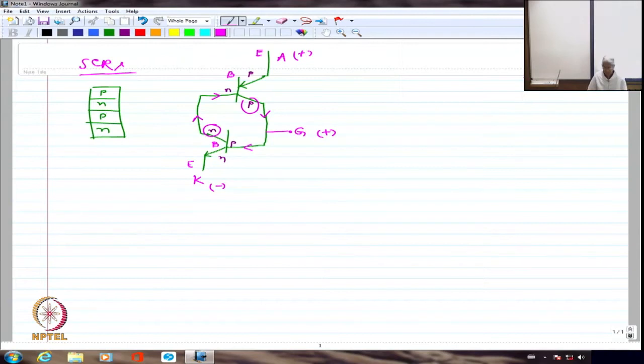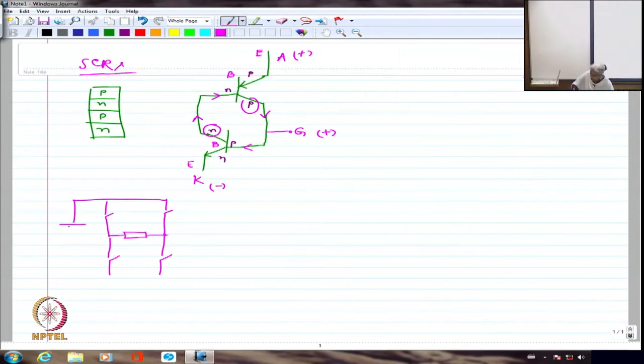If I am, for example, talking about an inverter, I had shown this inverter earlier also when I was talking about RL load and feedback diode. So this is an inverter circuit with a DC voltage as the input and AC voltage as the output. So this is going to be my inverter circuit. So if I say that this 1 and 1 dash correspond to positive half cycle when the current is flowing in this direction.